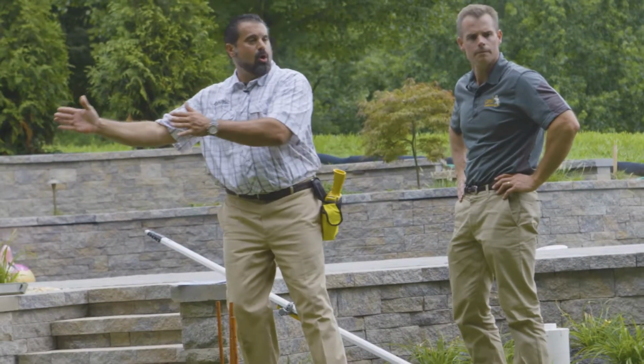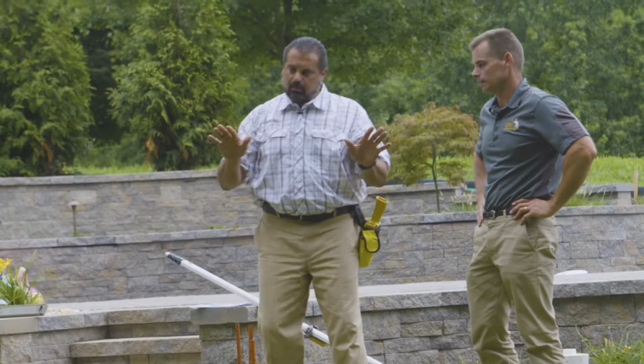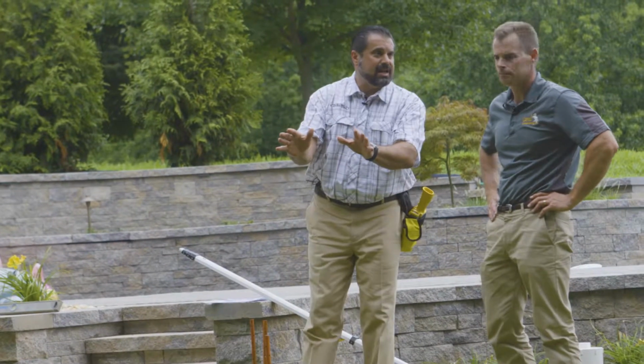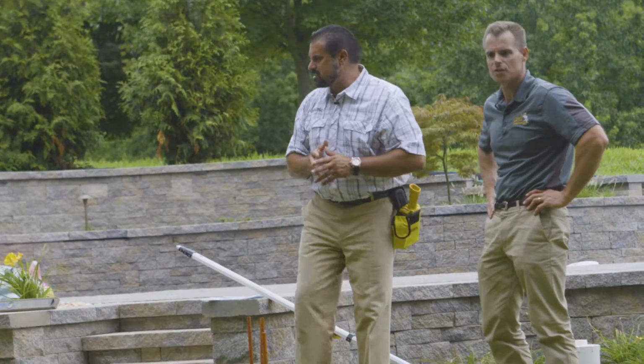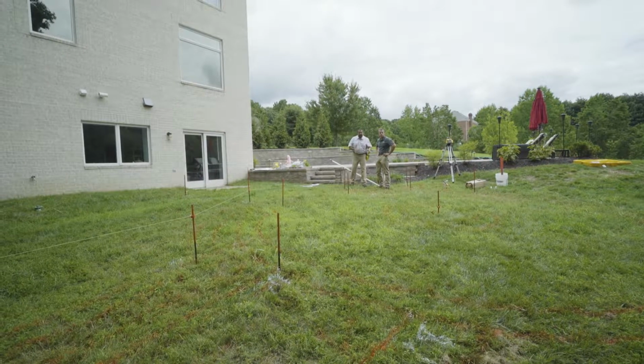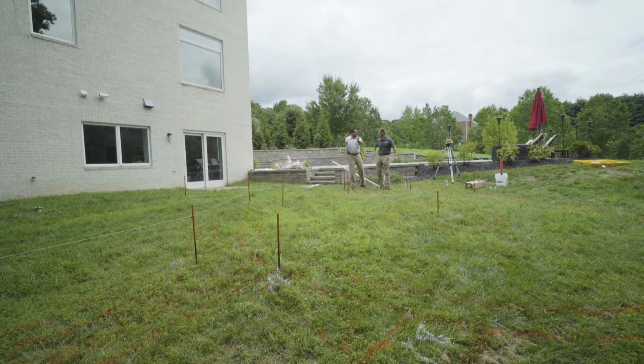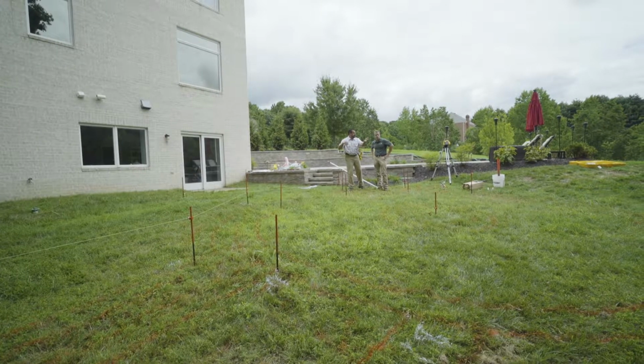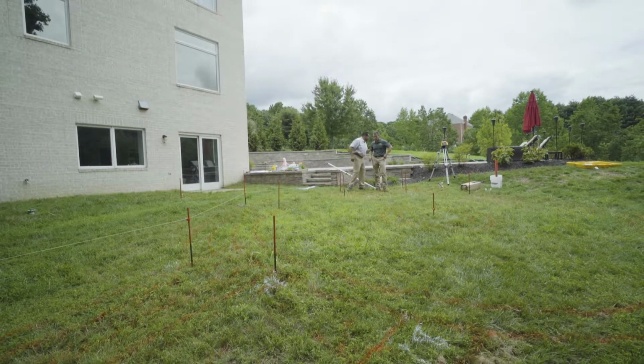So that's going to tie into the drain that's here. So we don't have any water sheeting over these steps. Right, we don't want that. No. It's still a retaining wall. It just happens to be in the shape of a set of steps. So level on the perimeters, drain to that area. All we have to do is get the rest of our collars in on this amphitheater seating, and then we can finish the lower landing. We sure can. Let's do it. All right.